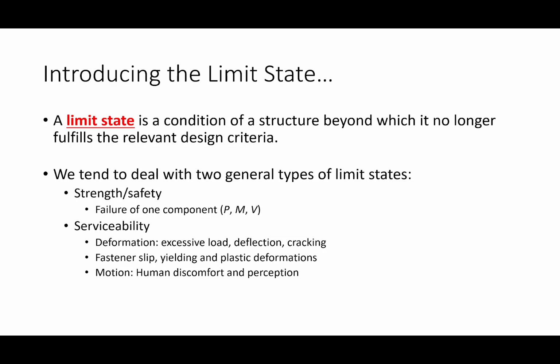How many of you have ever been in a building, a house, what have you, where you looked at the roof and the roof was plastered? How many of you have ever seen that before, like a plastered roof? I'm sure most of you have, okay? Well, if you're looking at the beams, a common service limit state is to take the length of the beam and divide it by a certain number, let's say 360. That's L over 360, a common deflection limit.